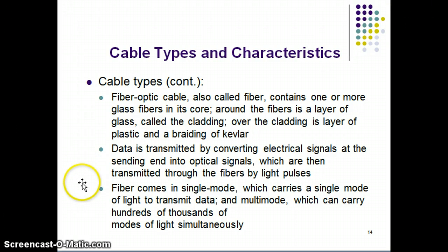Okay. Two major categories for fiber: single mode and multi-mode. Single mode, outside plant, long haul. The stuff that comes up from Chicago or over from Minneapolis, St. Paul, your internet service is going to be running on single mode prior to coming to your residence. Inside plant, larger facilities, they're going to typically be using this multi-mode cable. It's not as fast, can't go as far, but still much faster than copper-based cables, and the multi-mode's less expensive, easier to terminate than single mode.